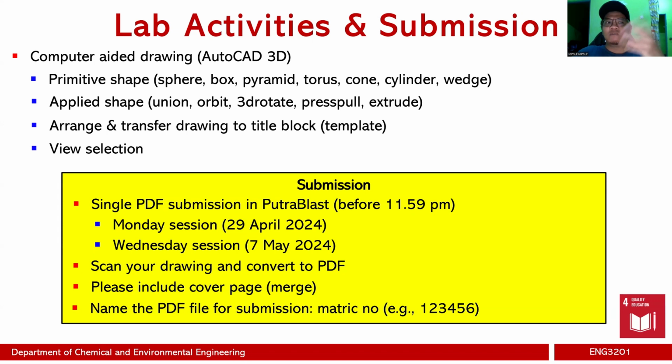And of course, we're going to cover primitive shapes, as I told you: sphere, box, pyramid, torus, cone, cylinder, wedges. What I have highlighted here is just a command in AutoCAD. So if you type this word, this is basically the command for you to prepare primitive shapes. After that, we're going to cover applied shapes.